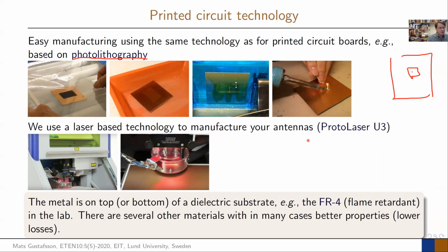And what we did is that we put this into a machine and removed the metal outside of that one. And that you can do by illuminating these ones with special light, and you use some chemicals. The chemical in here can remove the metal. So in the beginning, there is metal all over this place, like copper. And then by having illuminated some part, you can save that from this chemical process.